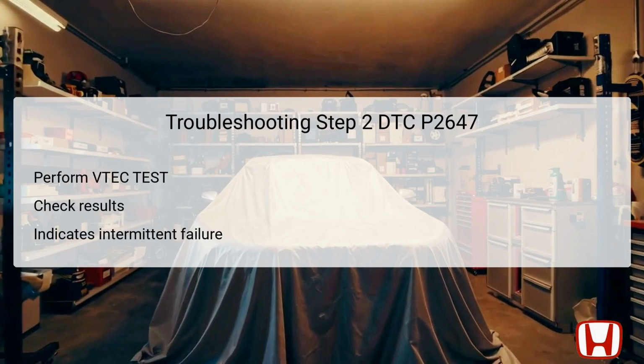In the second step of troubleshooting DTC P2647, a VTEC test is conducted using the Honda Diagnostic System, HDS. This test aims to verify the operational status of the VTEC system in real-time conditions and identify if DTC P2647 or any additional trouble codes appear.